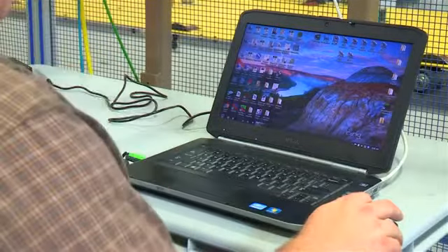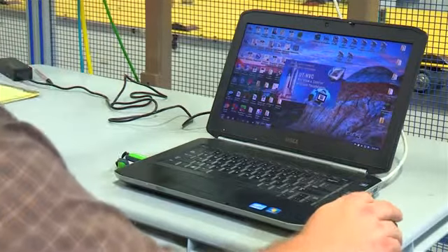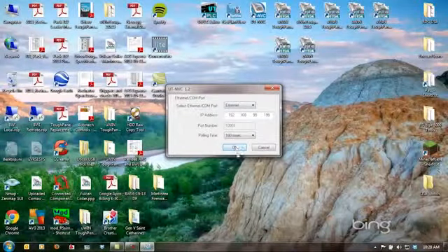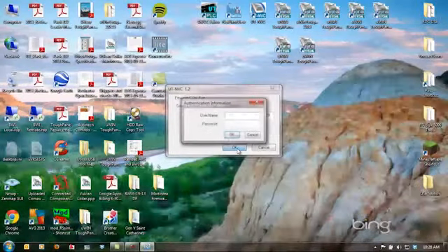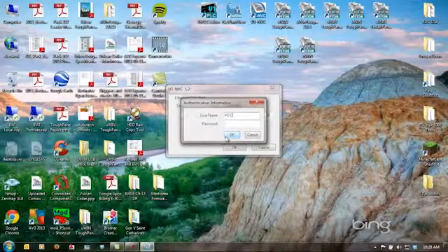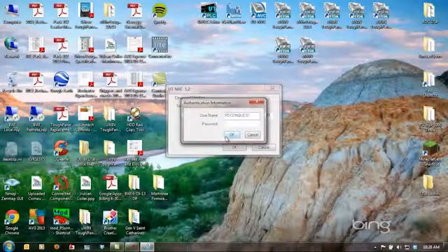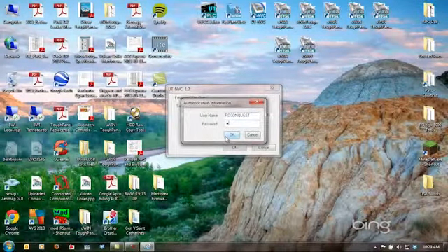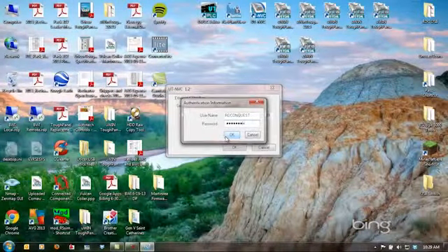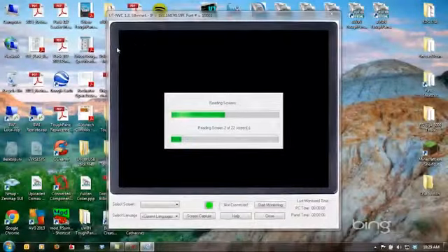Now, we can also remotely access the Uticor Toughpanel. We enter the Ethernet address and we'll hit OK. It'll ask for a login and password. This is created in the application, and you can control whether the user has access to just view or to view and control. In this application, I've got it set up for view and control.